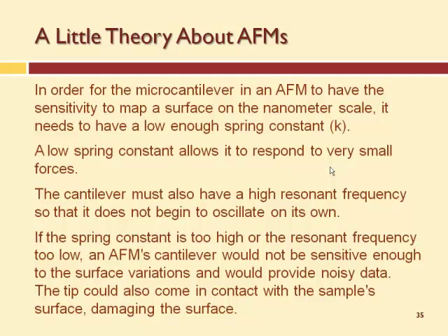All right, in order for the microcantilever in an atomic force microscope to have the sensitivity to map a surface on a very small nanometer scale, it needs to have a pretty low spring constant. It has to be flexible, so we're going to make them thin. The low spring constant allows it to respond to very small forces, like the force from an atom.